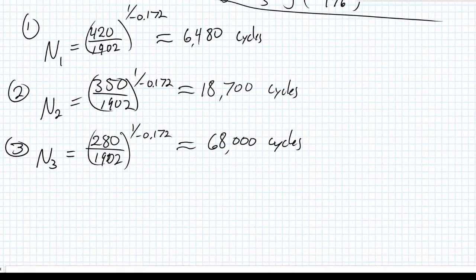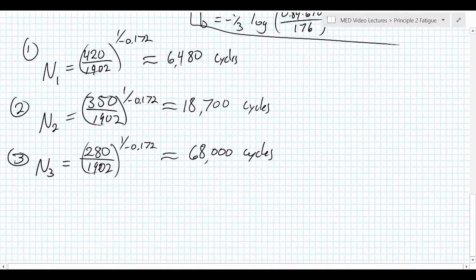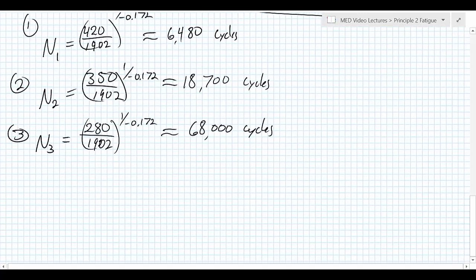All right. So at any of these loadings, we would not expect to see infinite life out of this product. But what we do see is that the stress is going to lead to failure eventually. So let's calculate the total damage from each of the cycles. So the total damage is, again, the sum of the number of cycles it's at that state compared to the number of cycles it should last till failure at that state.